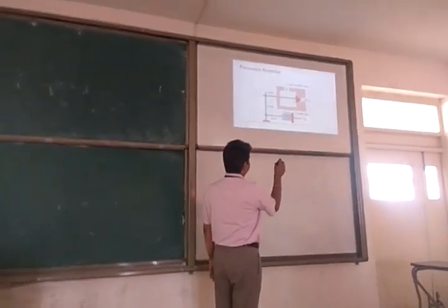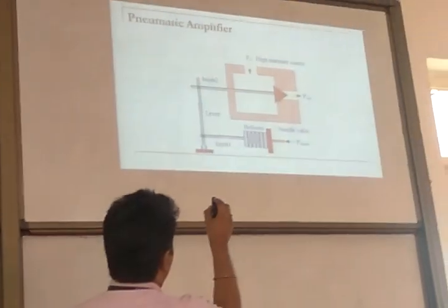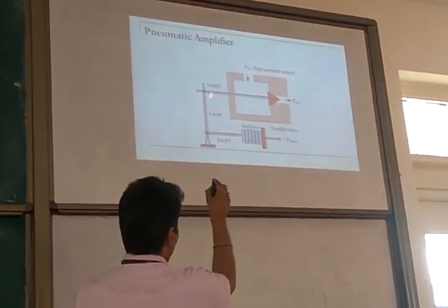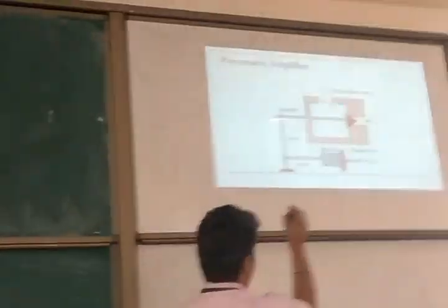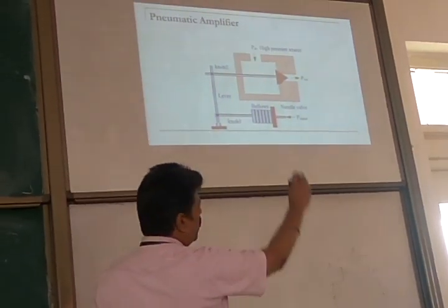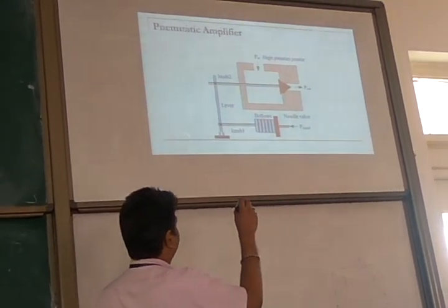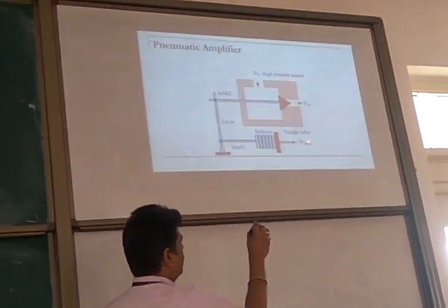The signal pressure is coming to blow the blower. The blower expands, pushing the knob to the left side. This pushes the lever towards the left side, and knob 2 is being pulled, wobbling the gateway for the high pressure source to go out. That's the working of the system.